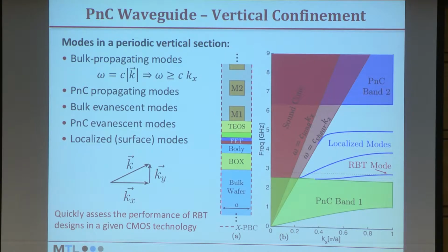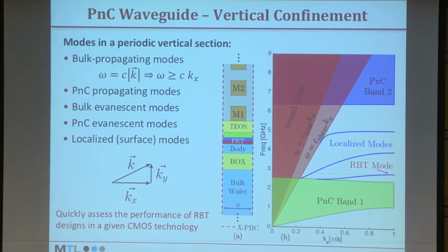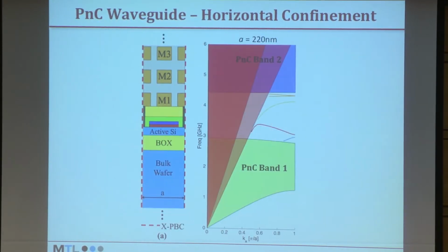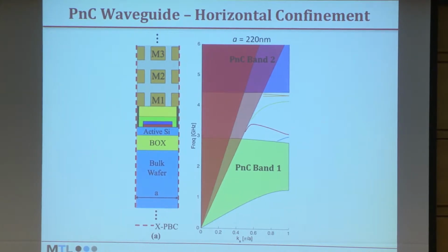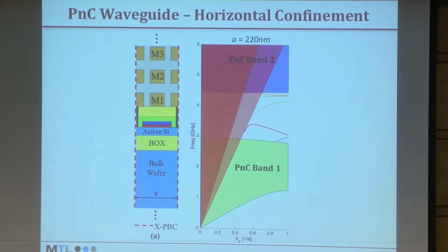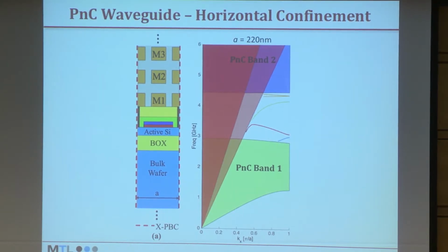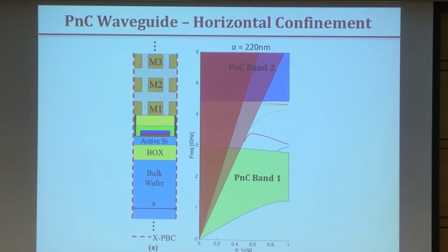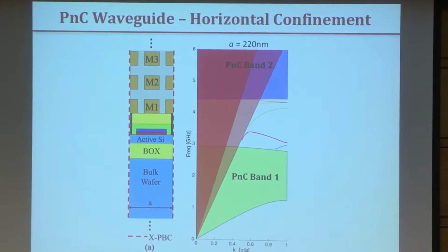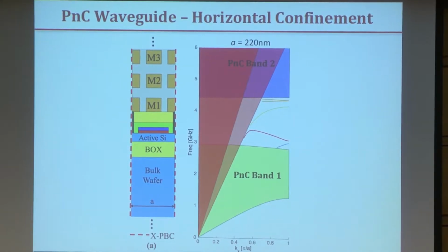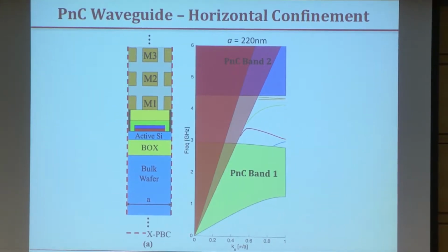But then the next step: how do we prevent them from propagating laterally? And so I said, OK, now I have a waveguide. What can I do with it? I know that if I change the dimensions slightly, all this dispersion relation will start shifting accordingly, because the wave equation transforms linearly under coordinate transformation.